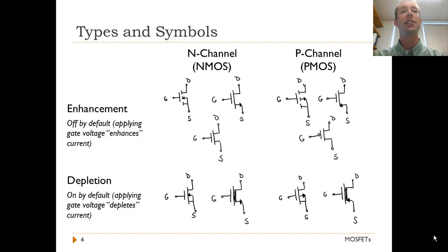Finally, in this last set, there is no arrow. Instead, the transistor type is indicated by the absence or presence of a circle at the gate. This set of symbols is typically used in the context of digital logic gates. The circle, or 0, at the gate of the PMOS device indicates that the device turns on when a low voltage, or logic 0, is applied to the gate.